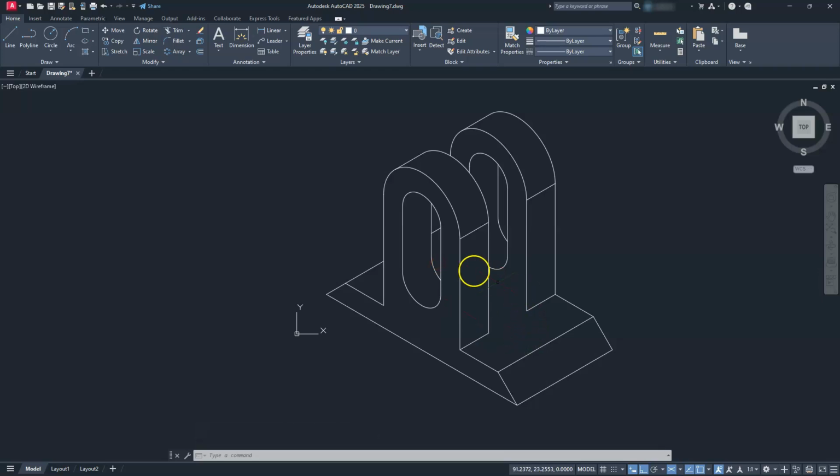All right, we need another line that's kind of shooting through here. And what I'm going to do, just to make sure that that line is the exact length, I'll create a line here. And then I'm just going to move this line from that endpoint going to here. All right, so that tells me where the edge of that will stop. So when I trim this, I know that it will not extend past that.